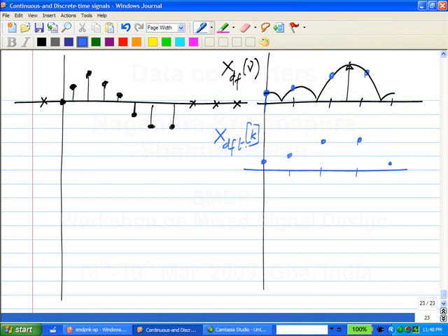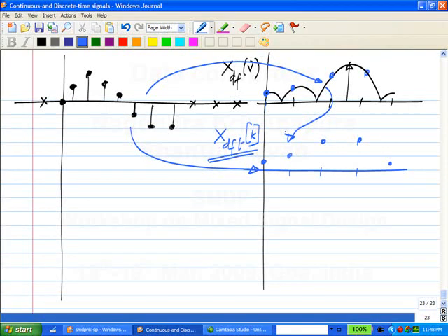So when I calculate the DFT, this is what I will be getting. I have taken a finite segment of it. You can think of this imaginary step where you are calculating the ideal Fourier transform at all points and then sampling them at these. Of course, you are only doing the calculation at these points. But because of the leakage, this is what you will get. So going from here to here is the same as going from here to this black curve and sampling the black curve. So the bottom line is sinusoid doesn't look like a sinusoid, and if I don't get the answers for a sinusoid, which is usually in page 1 of all textbooks, I will probably not get right answers to anything else.